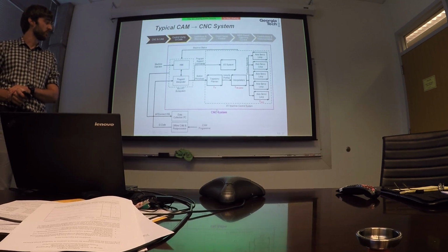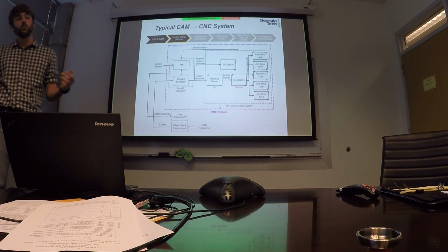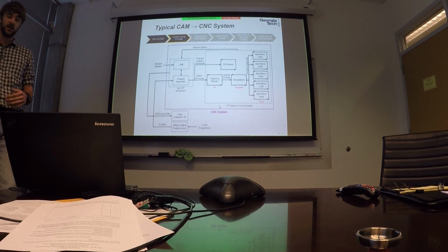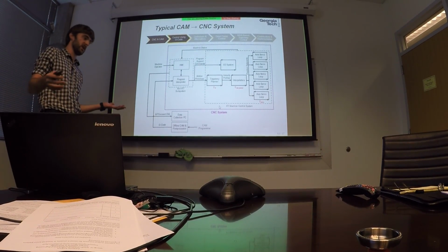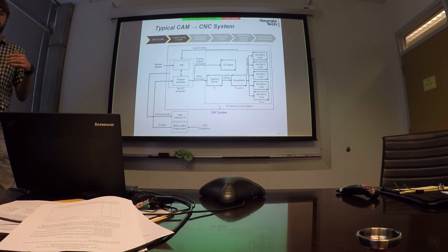So we would use a real-time system for safety critical control applications where, for example, we absolutely need to check the status of something every 1 millisecond, and we cannot tolerate any more than 100 nanoseconds of jitter.